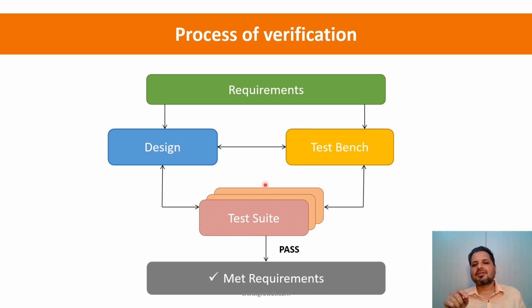So there will be various tests that will be built, and each one of them will utilize the capabilities of this test bench, which is the environment surrounding your design, meeting the same requirements, and it will be able to exercise the design in different scenarios and check whether the output is matching the actual expectation. When all of them pass, we say that it has met the requirements, right?